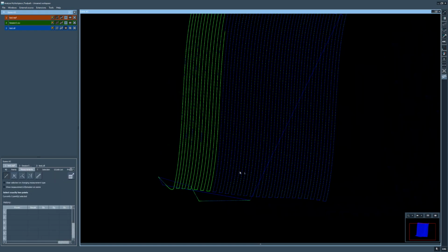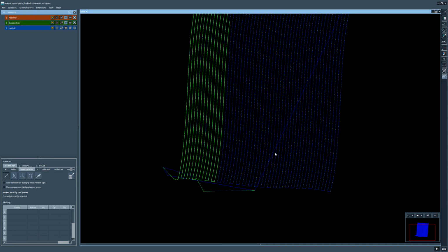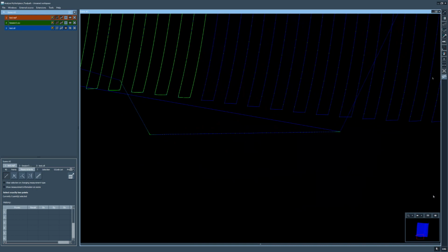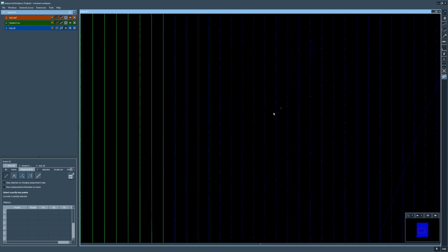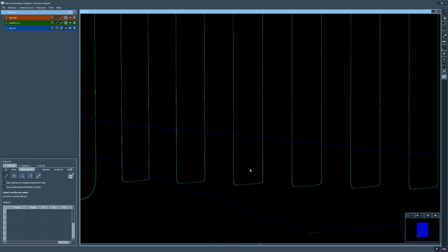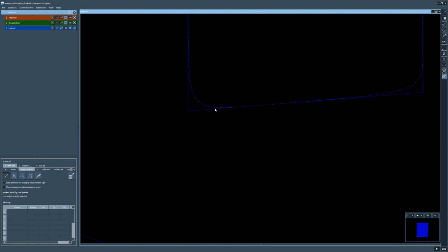measurements. You can execute measurements on all these points here. It doesn't matter whether the points are of the same model or not. And let's assume you have the following use case. You want to find out what's the distance between the commanded position here, or the actual position value coming from the MPF file, and the one that the CNC made out of it.